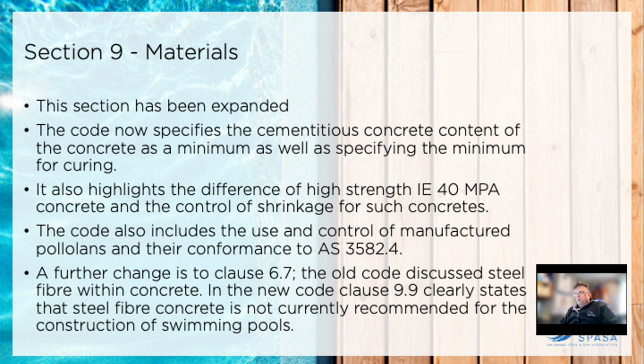The code also includes the use and control of manufactured pozzolans, which is essentially additives. So we're talking about fly ash and that kind of thing, and their conformance to AS3582.4, which is the code which governs those additives.